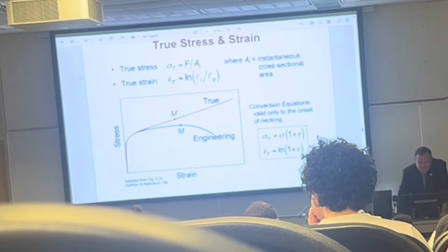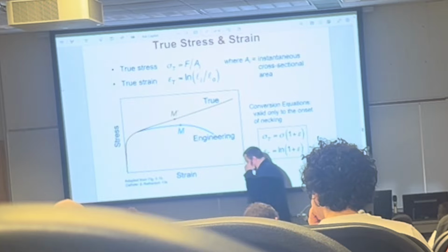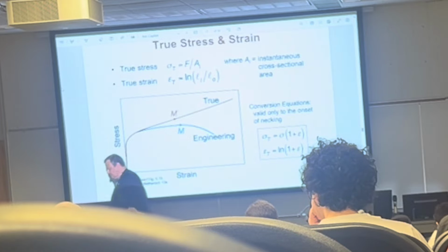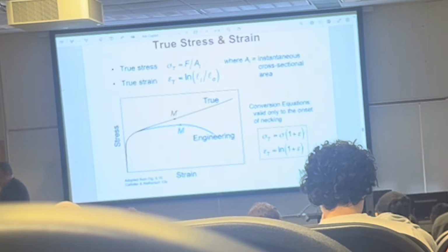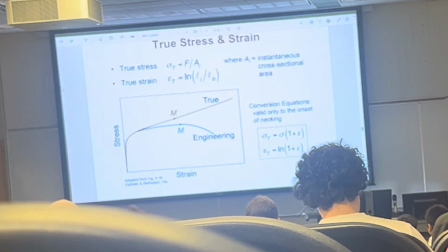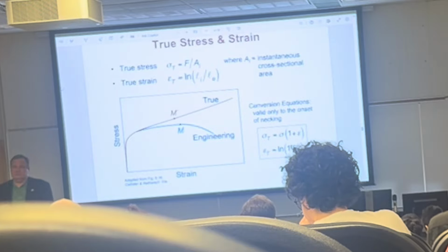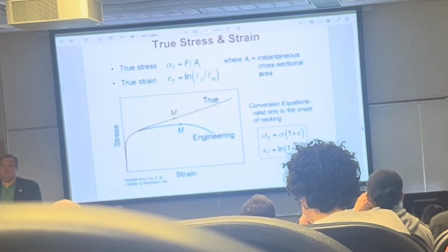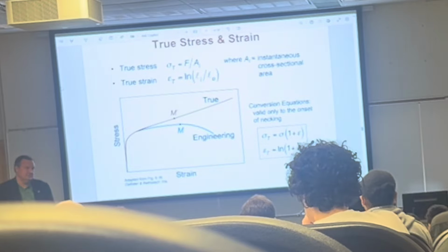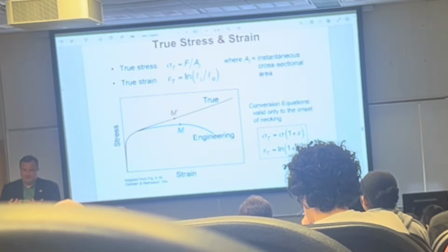All right, this brings us to a very important concept that is very often ignored because it doesn't have a lot of practical applications. There's a difference between engineering stress and strain and true stress and strain. So, what is the engineering stress? We take the load and divide it by A0, the original cross-sectional area before we even started deformation.